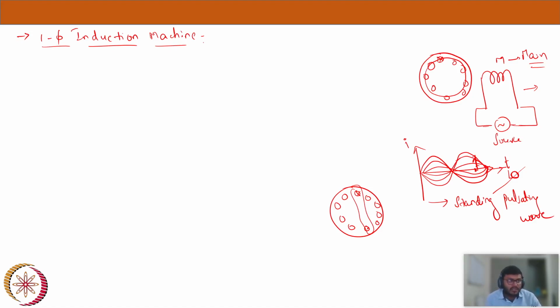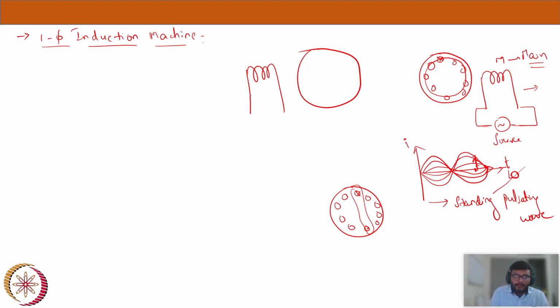So how will the current in the rotor be distributed? That's another point of discussion. This rotor current distribution will depend on the basic Lenz's law. It has to oppose the cause at any time. I can just draw it here so that you have an understanding. Let's say this one is our main winding, which is generating the time varying field, and we have connected this to a supply. It will be responsible for a current flowing through it, and whatever the current may be, this will be the axis of the field.